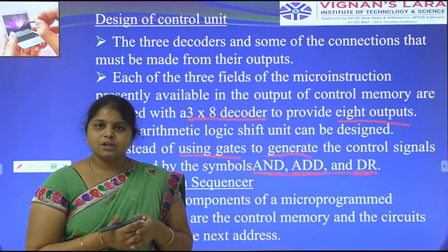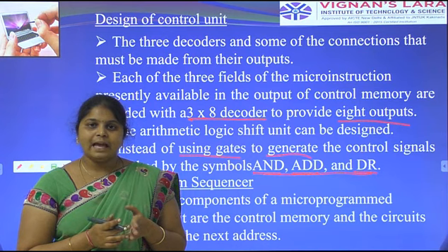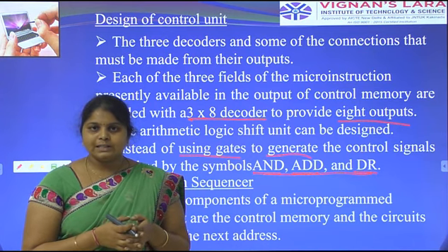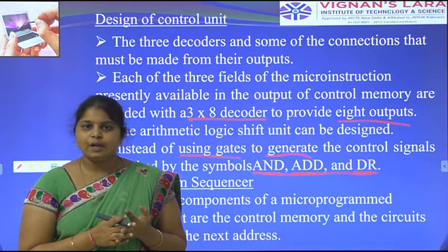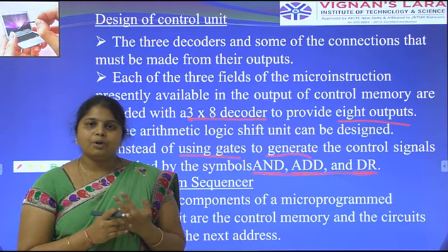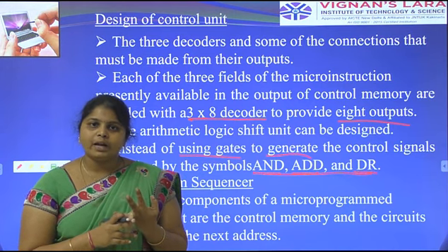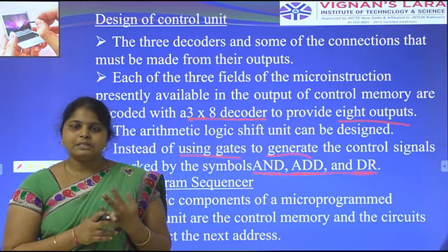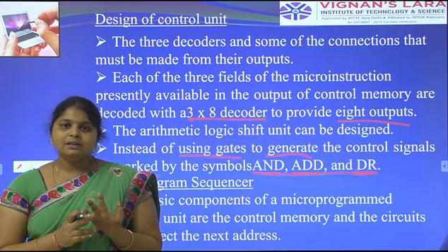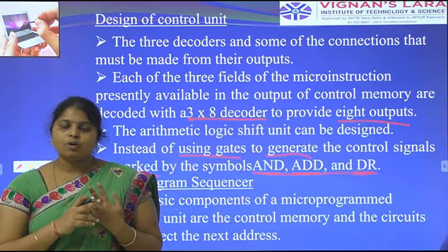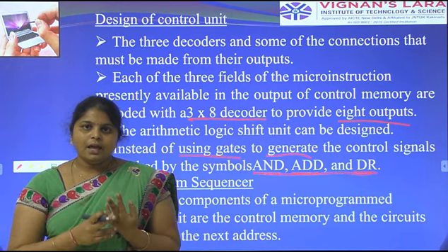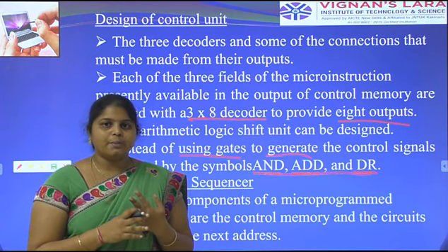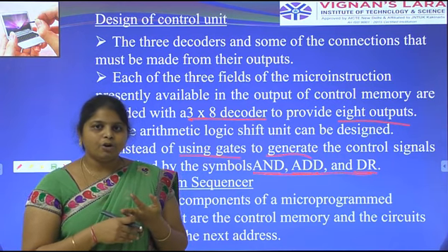Hardwired means it is logic implemented with hardware components such as flip-flops, decoders and encoders. Microprogram control means it is software, or a program. A microprogram is a set of instructions, and a set of instructions contains one or more operations. The whole operation of microprogram control is stored in the control memory.